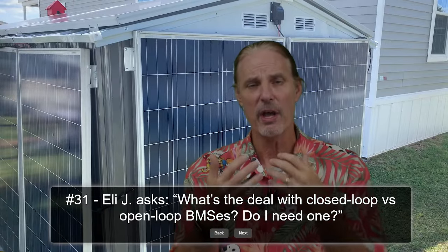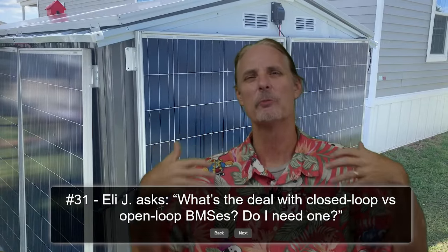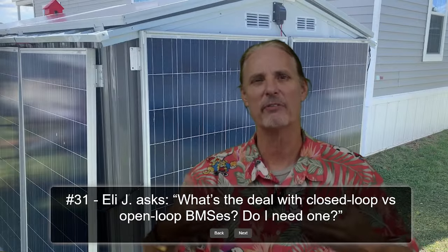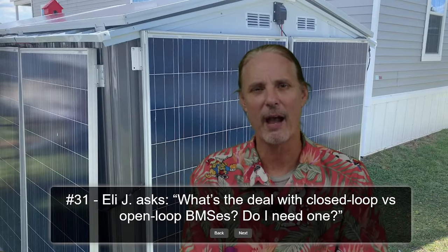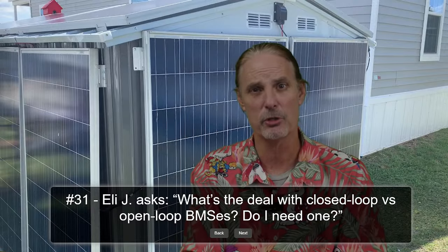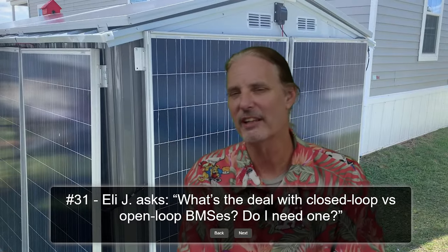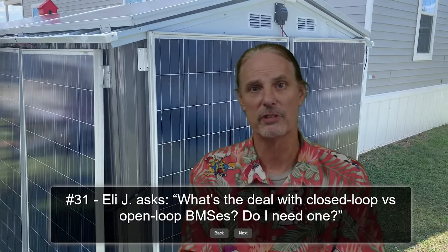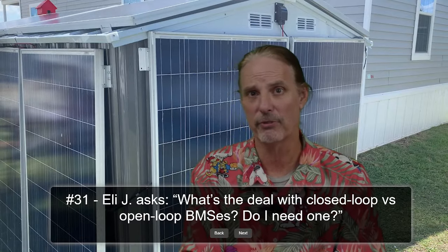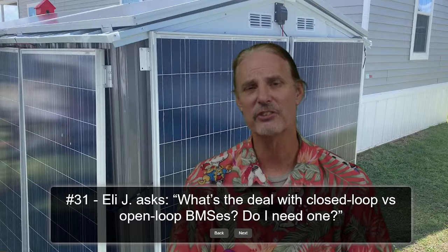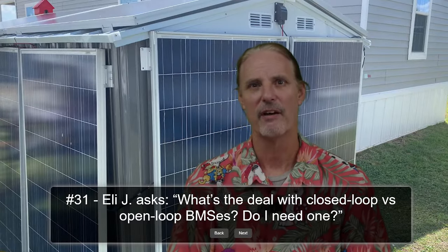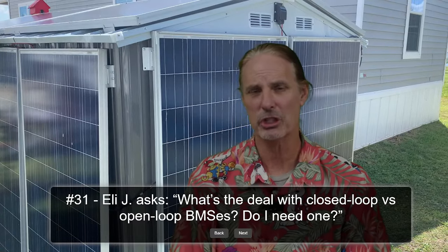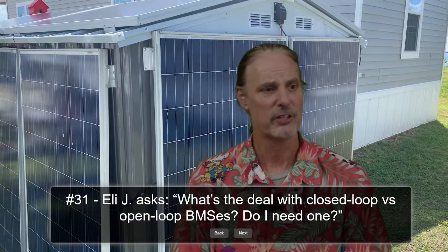Now, that doesn't change the fact that batteries are absorbing whatever energy is made available. But what you don't want is an excessive amount of over-generated power trying to flow into these batteries and cause them damage. There is a limit to what the battery BMS can stop, and those diodes and things can cut off and stop from flowing in the wrong direction. So there still is a reason to stop that type of availability, even though technically the BMS has cut it off. But you don't want to damage it by pushing that much voltage on it if you don't have to. So that is why.